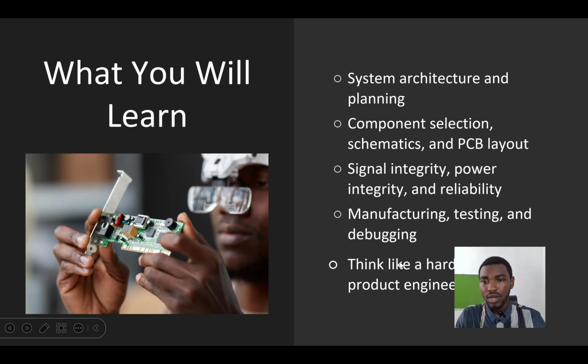Then we'll learn about manufacturing, testing, and debugging. We'll talk about how to generate our manufacturing files, how to communicate with our hardware manufacturer, either our PCB fabricator, or them sourcing components for us, and how to design our board for testability. Because most of the times you can have an electronics board, you can design a PCB board, and once the product is designed and shipped, you can find out that it's very difficult to actually test that product because you did not put testing in mind when designing the board. So we are going to do all that and learn how to debug also.